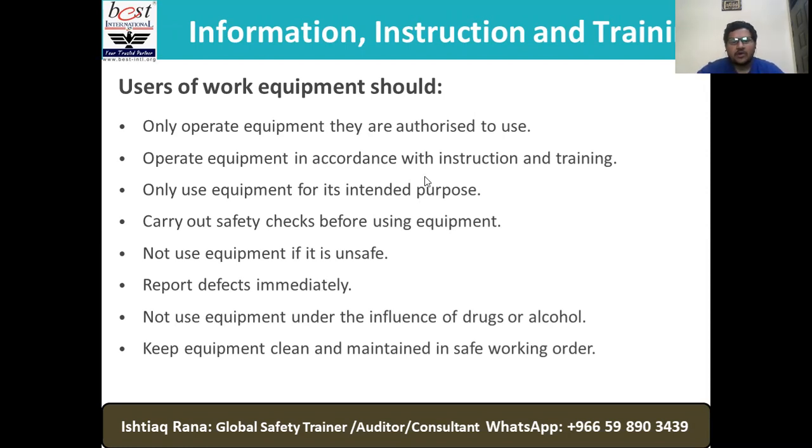Operate equipment in accordance with instruction and training, and that is written in the operating manual. Only use equipment for its intended purpose and carry out safety checks before using equipment. But carrying out a safety check does not mean tick, tick, tick, like I discussed several times. Do not use equipment if it is unsafe, and report defects immediately.